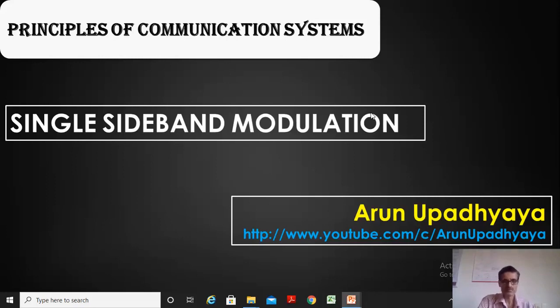Now, we can suppress the carrier because, as explained in my previous videos, the carrier doesn't represent any modulation. It's an unmodulated carrier. So we can suppress the carrier and transmit only two sidebands, and that method is called double sideband suppressed carrier. The carrier is removed. The advantage of double sideband suppressed carrier is that we save a lot of power. The power required to transmit the carrier is not required while transmitting the two sidebands. So that is the advantage.